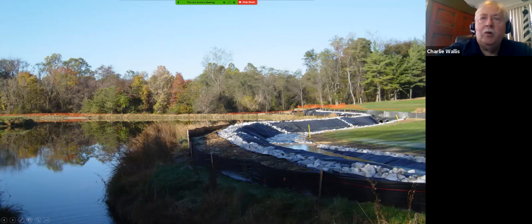We've talked about needing to work in the dry. Sometimes diversion channels are needed, and it can be a large drainage area, and so the diversion channel can be quite large to divert the flow around the site. This is the dam, and the off-site drainage area is diverted around the dam so that the work can continue, and then this reservoir would be lowered and dewatered.